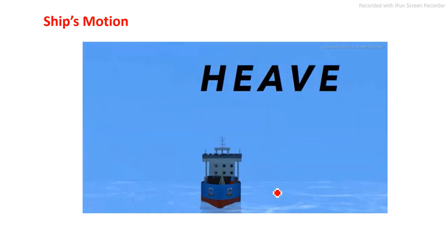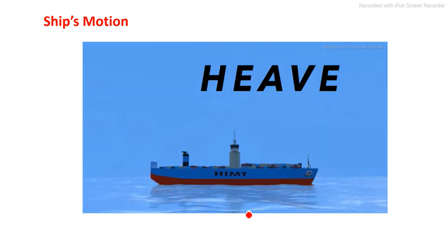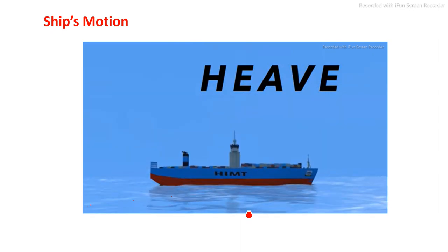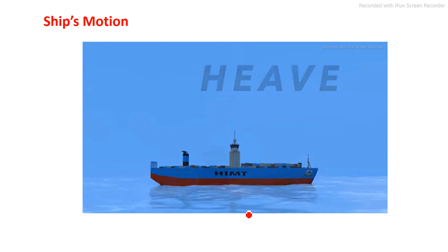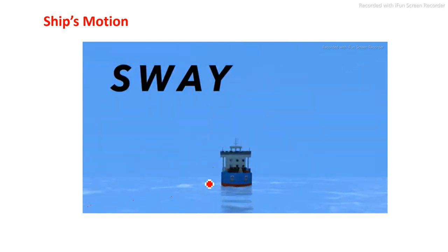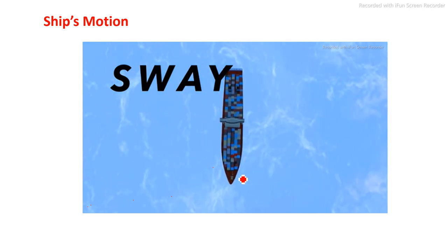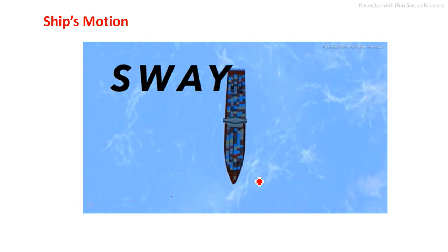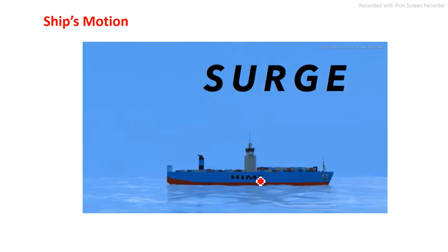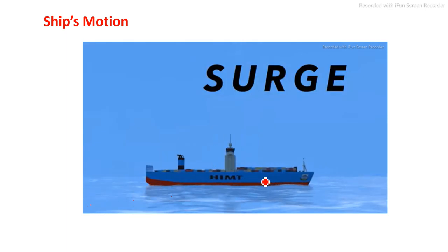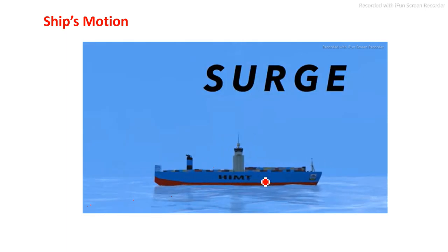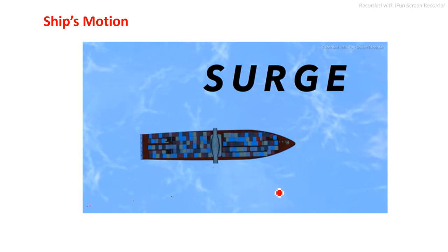Then this is heaving. The ship is moving up and down. Then this is swaying. The ship is having a lateral movement from right to left. And then this is surging. The ship is moving backward and forward.